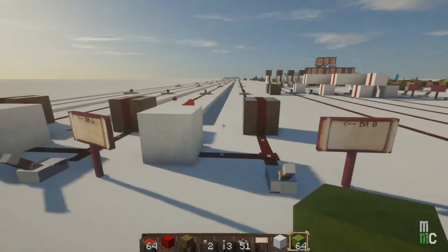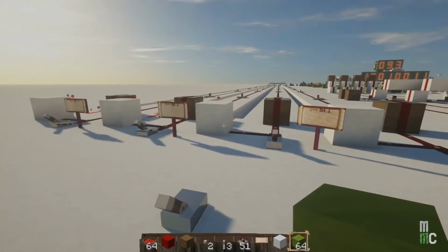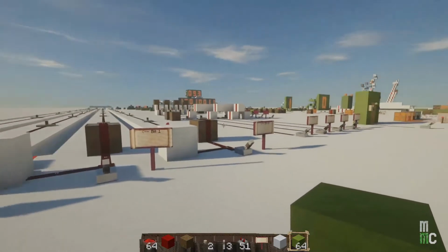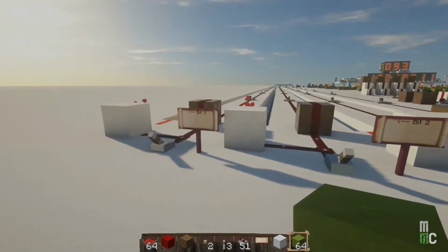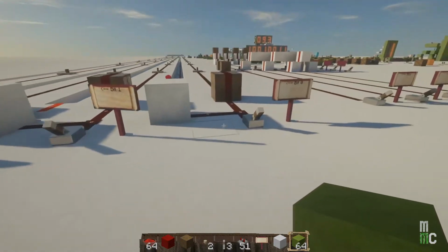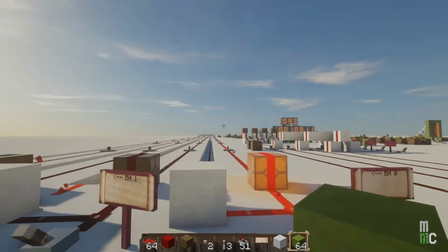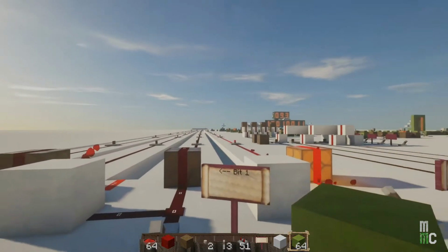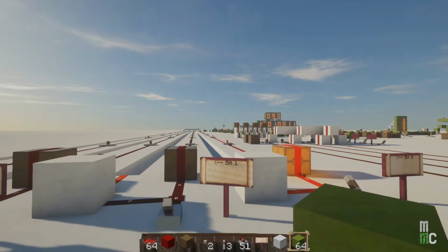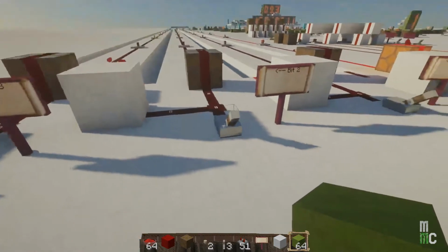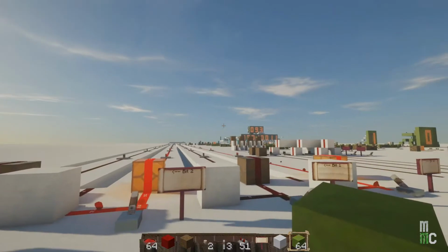For this next part of the project, what we'd like to be able to do is take this 4-bit bus that we have here, bit 0, 1, 2, and 3, and put whatever we want on this bus, such as a 1, and have a big display here show in base 10 decimal whatever is on this bus encoded as a BCD number. So that would be 1, add a 4, this would be 5, and so forth.